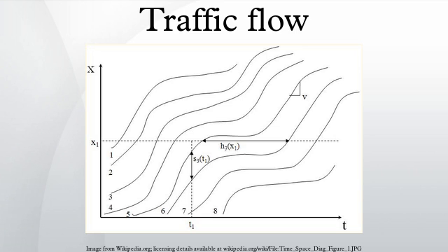Once vehicles arrive at rate A starting at T1, the queue will begin to clear and eventually dissipate. State A has a flow rate below the one-lane capacity of states D and E. On the time-space diagram, a sample vehicle trajectory is represented with a dotted arrow line. The diagram can readily represent vehicular delay and queue length. It is a simple matter of taking horizontal and vertical measurements within the region of state D.